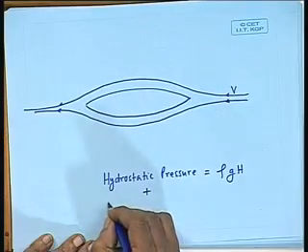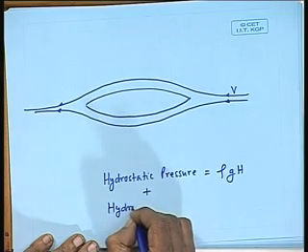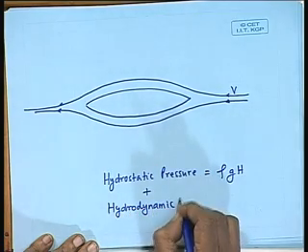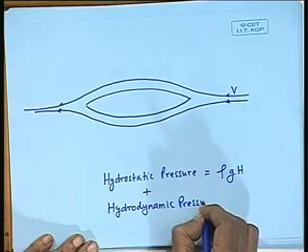But when there is a flow past the body, this pressure would change. This rho g h will be there. Over and above this, there will be some pressure which will be the hydrodynamic pressure because of dynamics of water around the body. Okay. So, the total pressure acting on the body will be hydrostatic pressure plus hydrodynamic pressure, right.